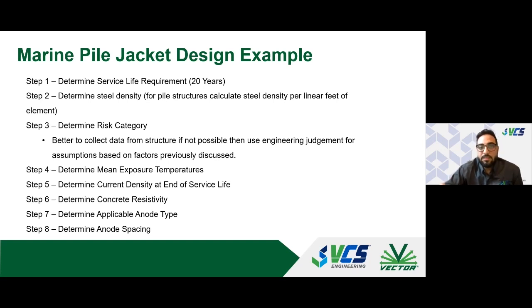And then step three is determining the risk category, figuring out how much chloride content we are dealing with at the reinforcement depth, because as you saw, that significantly affects our risk category and the design current requirement for it. So it's always good to go out to the structure and collect powder samples or core samples and send those to the lab to get analyzed, to have a real idea of how much chloride content that structure is exposed to.